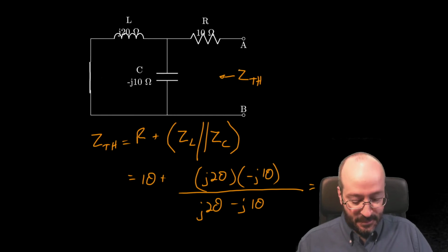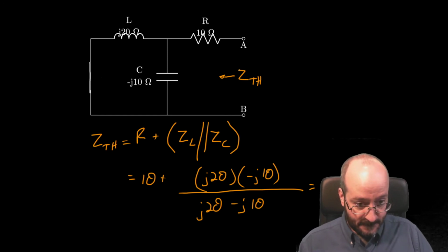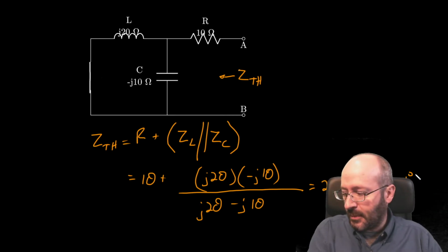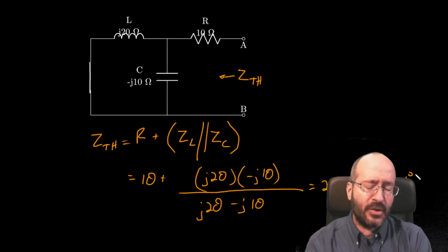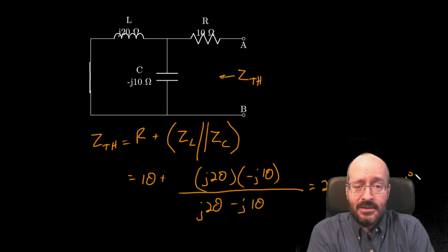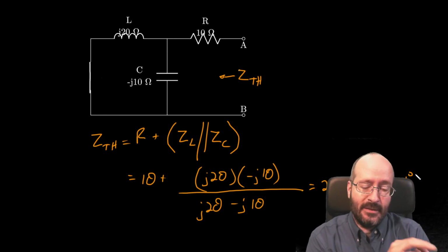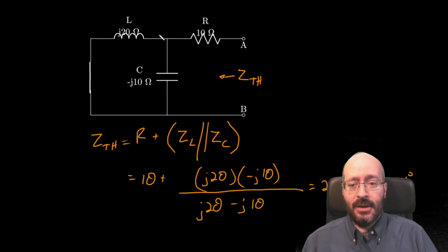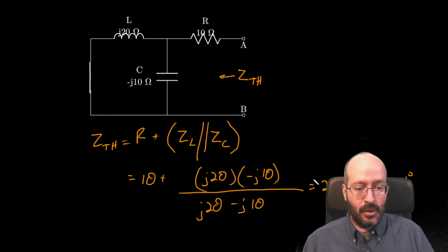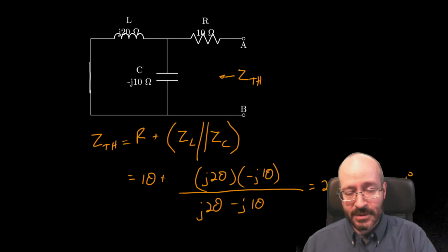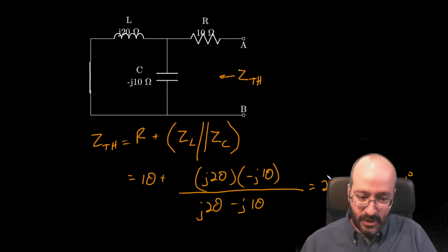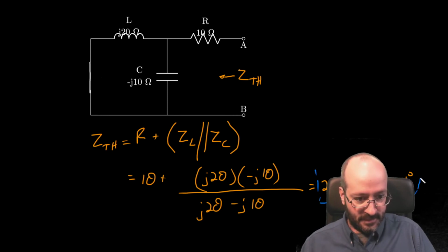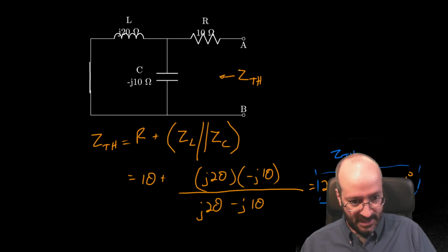That's where things get ugly, because we have 22.36 at an angle of -63.4 degrees. Let me just scroll over. Yep, no crazy exponents on the angle. So it's an impedance, and that one's in polar form. There's nothing wrong with depicting the impedance in polar form. We tend to do it in rectangular because we find individual components in rectangular form. But as long as it's locating the same point on a two-dimensional plane, it's an equivalent number. So there's our second intermediate result that we needed.